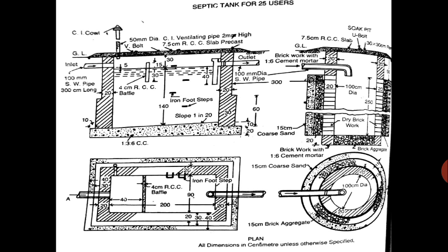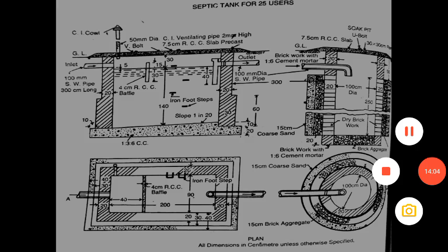But in the case of the septic tank, they have used 1:4, because there we are using first class bricks. Of course, whenever you are calculating first class brickwork, the price of first class brickwork and the price of second class brickwork, they have made separate columns in the PWD SR rate, and you have to use it accordingly. Maybe the soak pit we will continue in the next class.